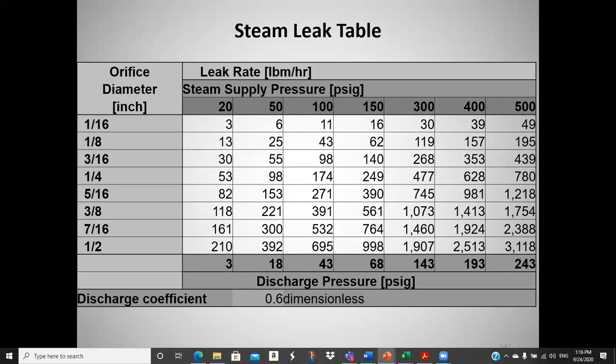This leak in the field is equivalent to a 3/16 diameter, and I know my pressures. Usually I know my steam pressures; I can get a pressure measurement. The reason I'm asking is because I took that Napier's equation, and instead of doing 51.43, I did 60 for the 60%. And at 400 psi, which in Napier's equation you use psia, so you have 14.7, and 1/4 inch, which is what we were given in the Word document, if you do the pi r squared for area, the numbers don't match the table.